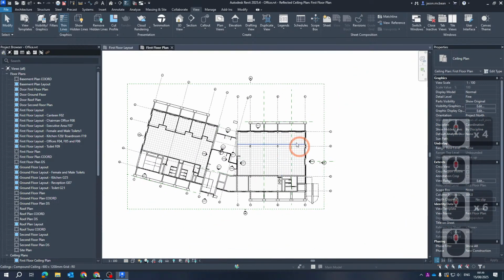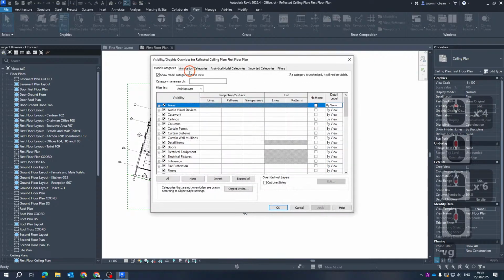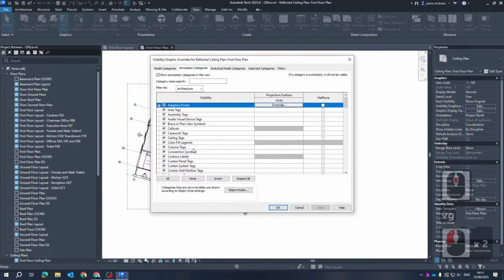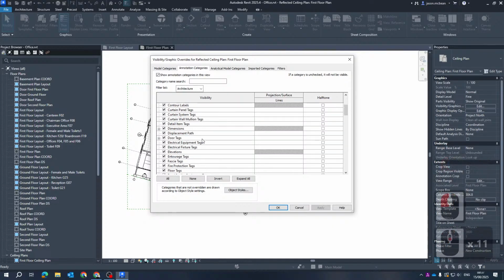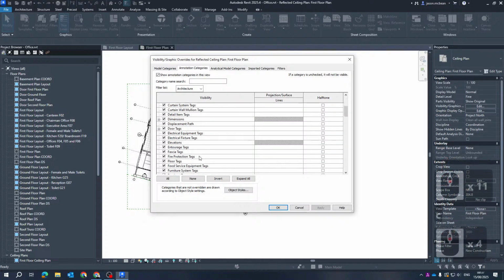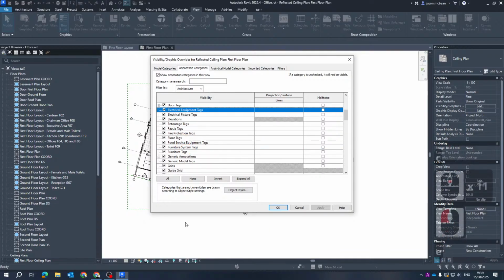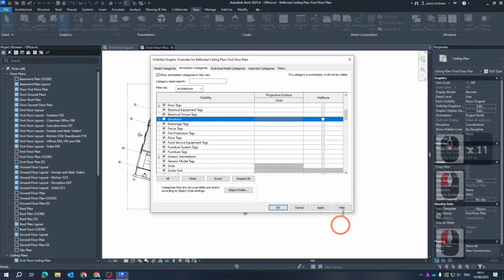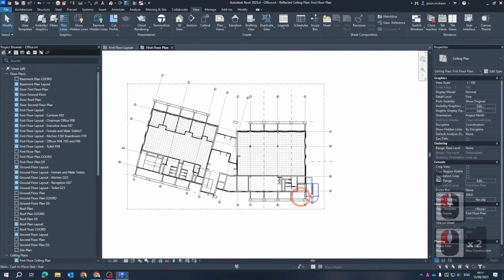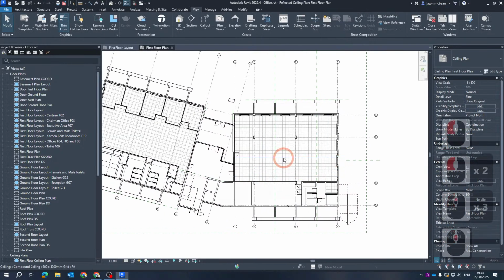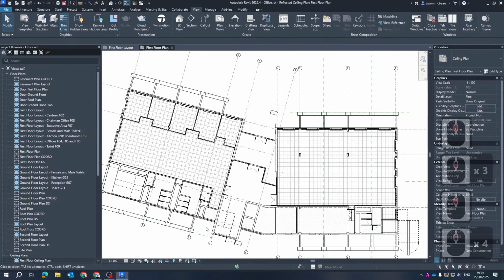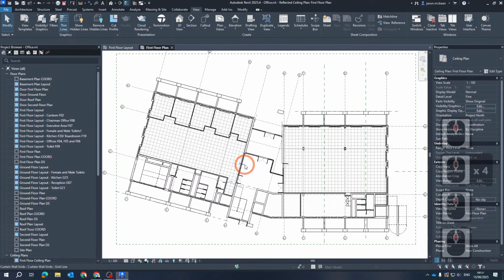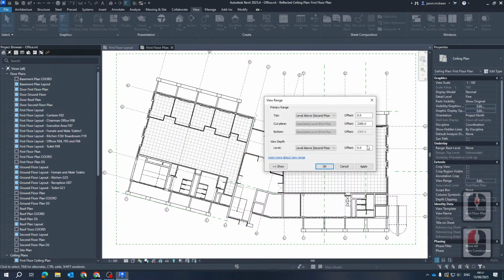And once again, you can see all the elevation markers are there. So we never really show elevation markers on our ceiling plans either, just section markers maybe, but ceilings no. Okay, so I mean elevations no. So elevation markers, we will switch them off later, we'll use them later if we're going to do interior layouts, but we'll get to that later on. Okay, so you can see this building already has some ceilings in, and I'll discuss that in a minute. But right out as we create the view, Revit does give us good information to start with.